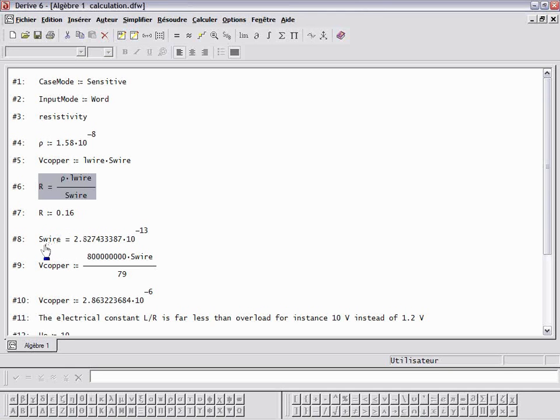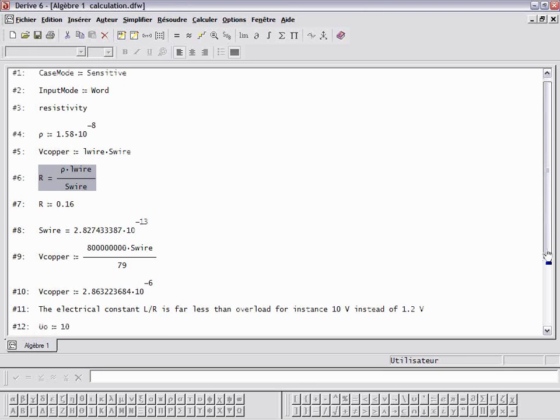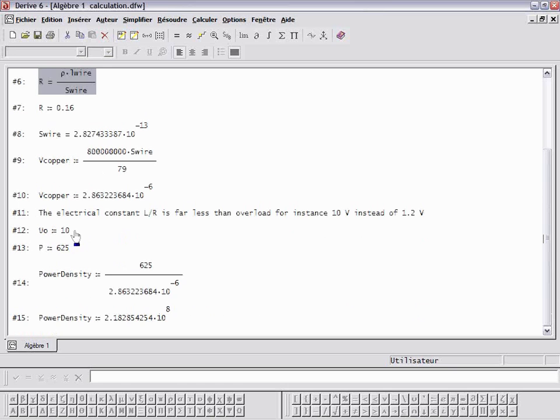In QuickField, we have the possibility to calculate the resistance easily. So I've calculated with QuickField that it's 0.6 ohm. From then, I can get the length of the wire. As I know the surface of the wire, I get the volume of copper.